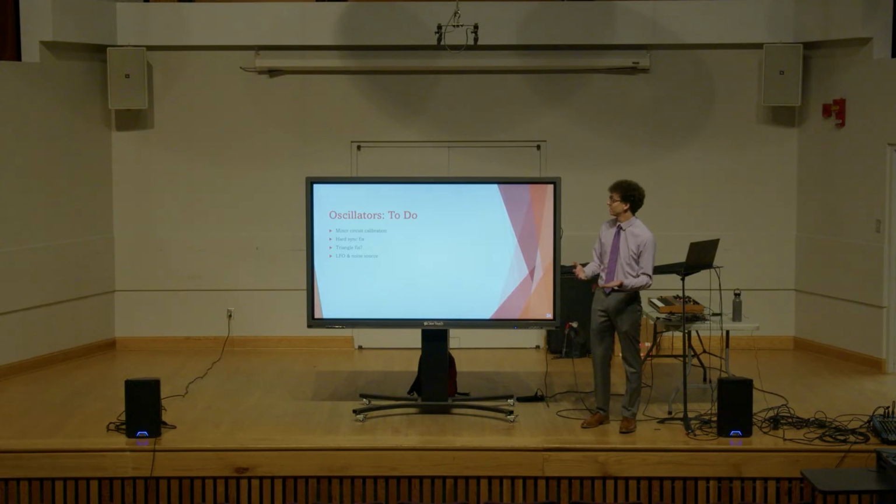I've got to fix that hard sync like I mentioned. If you looked really closely, you would see that the triangle has a little notch on the top where the tops don't quite meet each other. I'm not terribly worried about that. It sounds well enough like a triangle wave. It's not adding that much harmonic information, but if I ever get it in me to fix it, then I'll just go ahead and do it. I have an idea if I'm going to do that. And then I have to now start considering how I want to implement low-frequency oscillators for modulation purposes, which I will talk about later.